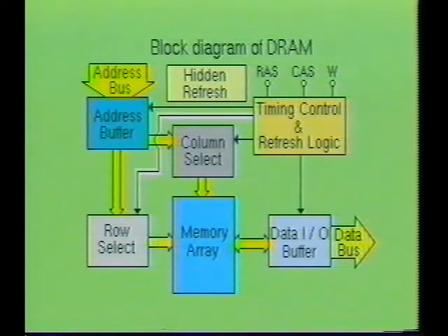Depending upon the timing of the system, the CAS input may be held low for several microseconds, during which several rows may be refreshed. There are other variations of refresh methods, but these variations add a fair amount of complexity to the dynamic RAM IC. Fortunately, however, there are refresh controller ICs available for many different dynamic RAM sizes and configurations.